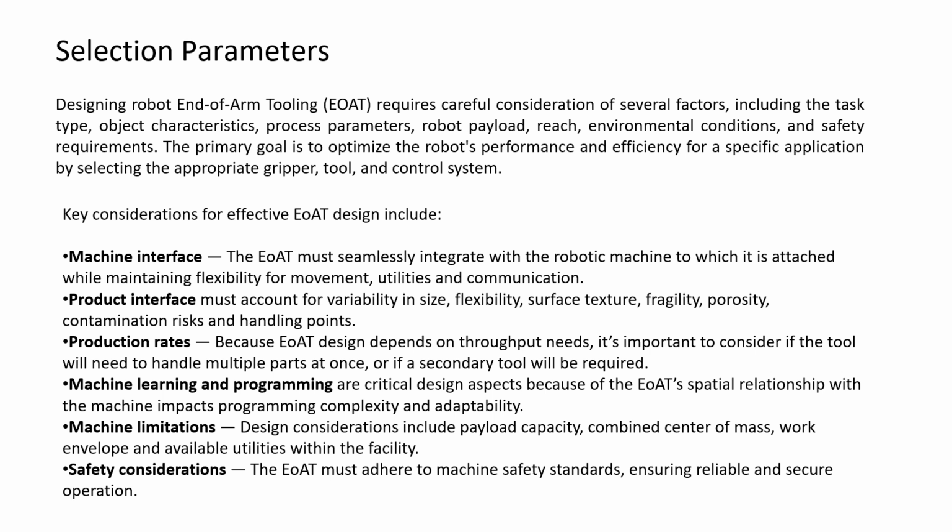Then machine limitations, so definitely payload capacity of the robot, then CG of the mass, because we cannot have something, let's say we are designing some end of arm tooling and it is having a two cantilever to the wrist, then it will create the excessive moment, so we need to take care of the CG also.